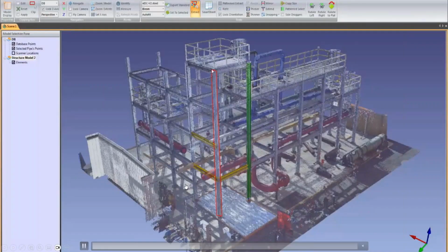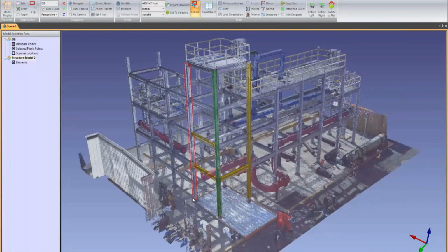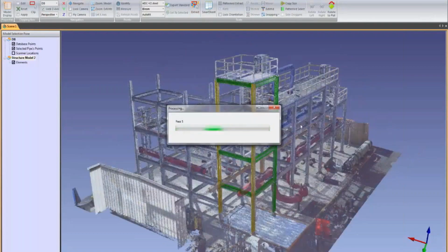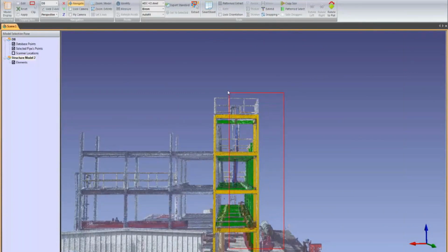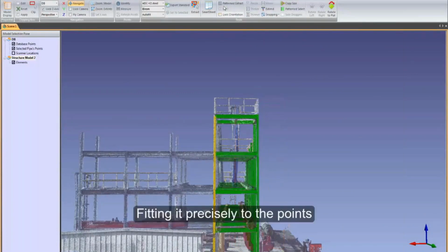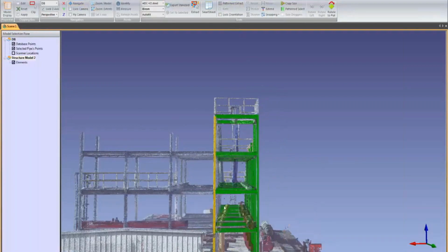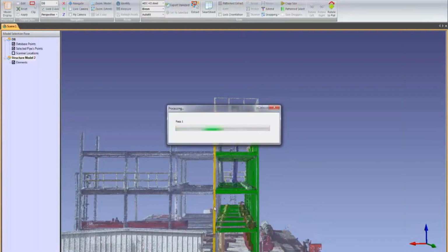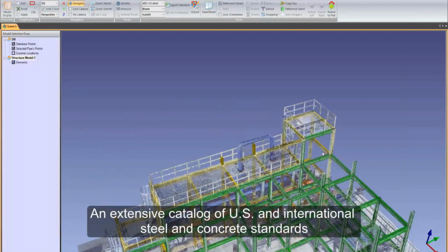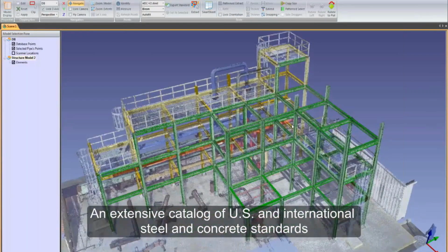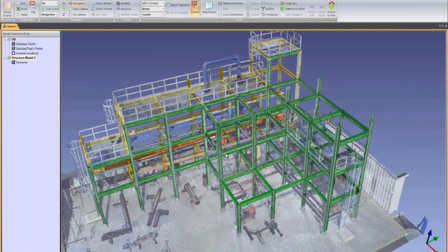The structure one is pretty cool. You could designate or highlight an area of a profile. So there's the steel profile, and what we'll do is you gave it a base to extract, and it has extracted the corresponding geometry. Here you can see we can do a patterned extract, and it will extract those members for you in CAD. That is CAD, what you're seeing on the screen. No one drew that. Based on the properties of the point cloud, it was extracted, and you can see it did a pretty good job of that.